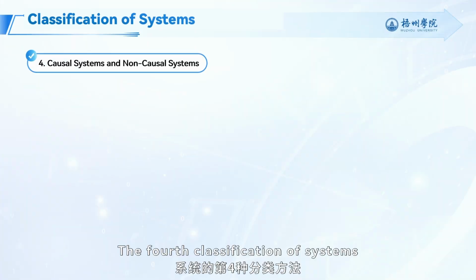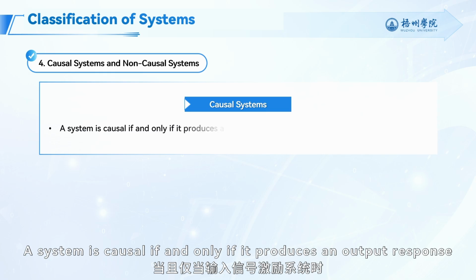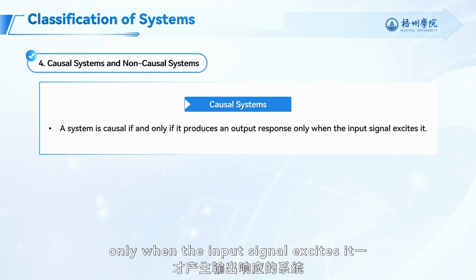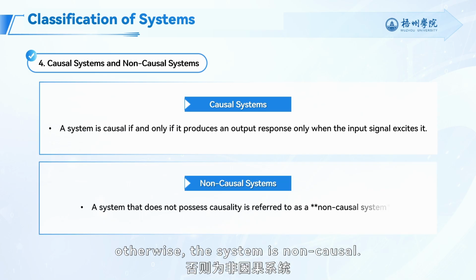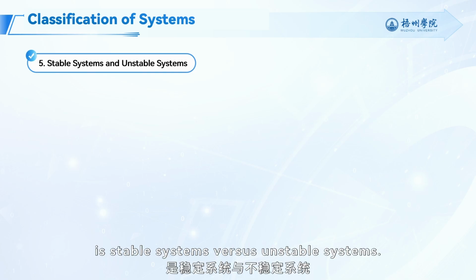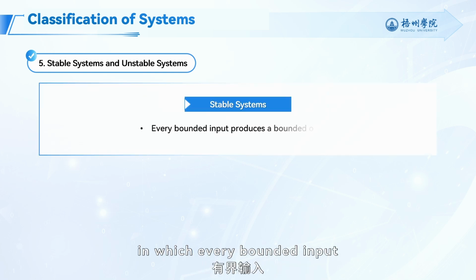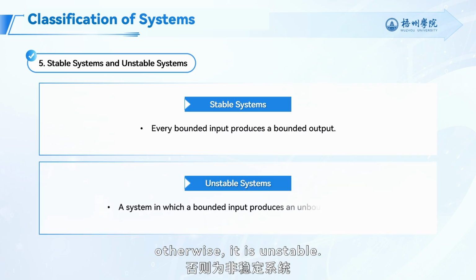The fourth classification of systems is between causal systems and non-causal systems. A system is causal if and only if it produces an output response only when the input signal excites it. That is, the output cannot occur before the input. Otherwise, the system is non-causal. The fifth classification method is stable systems versus unstable systems. A stable system is one in which every bounded input produces a bounded output. Otherwise, it is unstable.